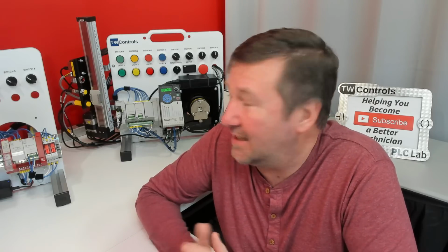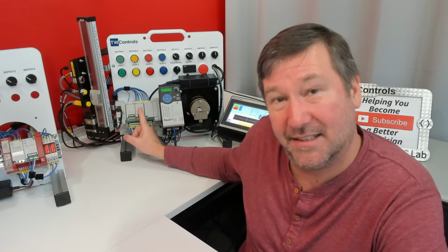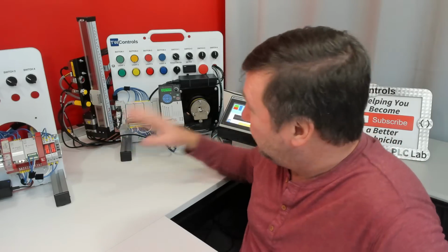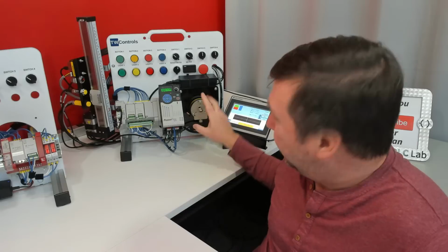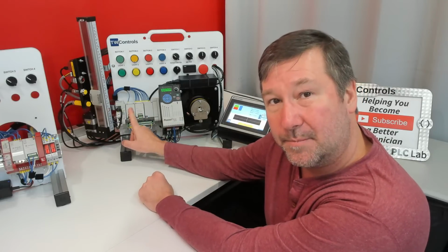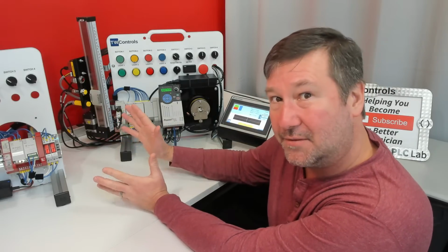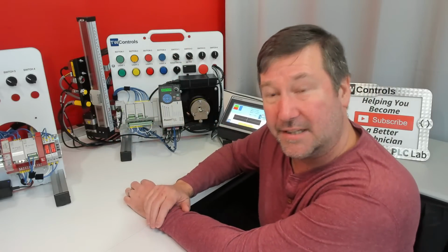So you can select Ignition, and it'll have drivers in there. Actually, in our last live stream, or two live streams ago, we talked about trending. We were connecting Ignition, which is the SCADA, to the PLC, and then we were reading the drive commanded speed and the encoder speed. So we're taking these two field devices, collecting them here, putting them into some type of value that works for what we're looking for. And then we were shooting up to Ignition, or you could also arguably use an HMI for that.